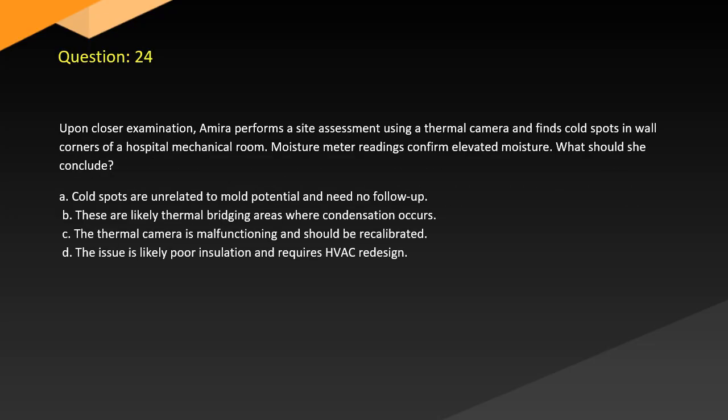Question 24. Upon closer examination, Amira performs a site assessment using a thermal camera and finds cold spots in wall corners of a hospital mechanical room. Moisture meter readings confirm elevated moisture. What should she conclude? A. Cold spots are unrelated to mold potential and need no follow-up. B. These are likely thermal bridging areas where condensation occurs. C. The thermal camera is malfunctioning and should be recalibrated. D. The issue is likely poor insulation and requires HVAC redesign.